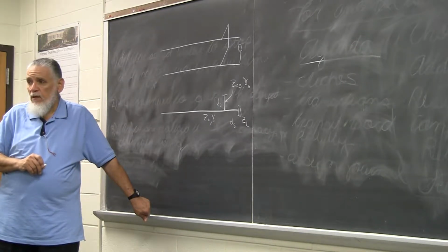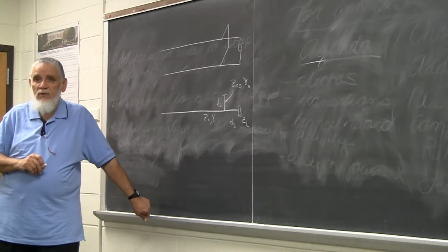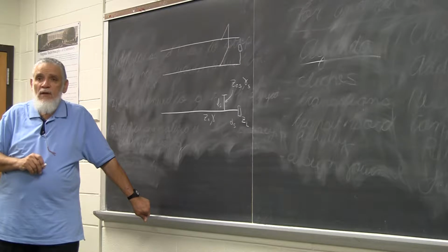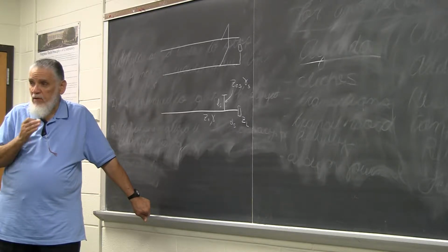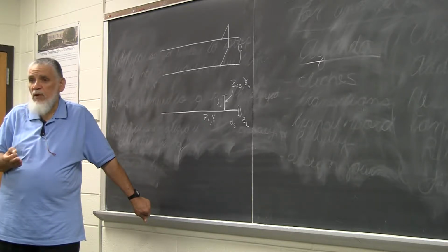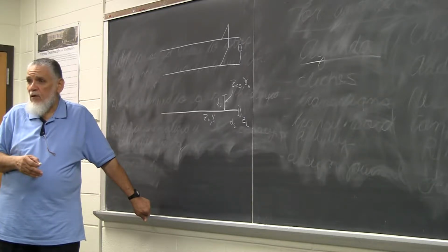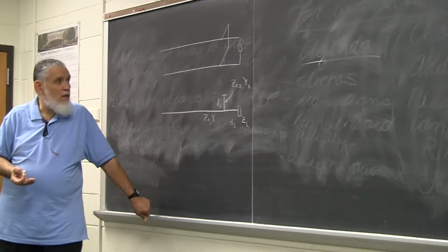Right? Using a reactance means another transmission line, which we call the stub, and we use that stub to produce the reactance that we need. So we take care of the resistance by moving down the line until a particular location. Once we are in that location, the resistive part or the real part is taken care of. The reactive part can then be taken care of by adding either a series reactance or a shunt reactance. And once we tune, then we are down to Z0.